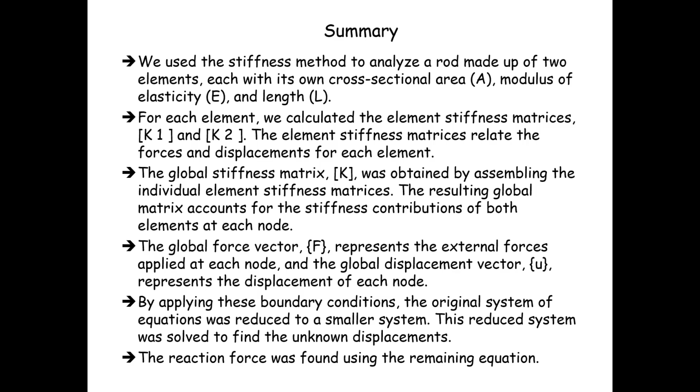With the global matrix assembled, we could then establish the global force-displacement relationship, relating the external forces to the unknown displacements. The key to solving this system was applying the displacement boundary conditions. By identifying the known and unknown displacements and forces, we were able to reduce the original system of equations down to a smaller, solvable system. Finally, we solved this simplified system to determine the unknown displacements. With those values, we were able to use the remaining equation to calculate the unknown reaction force.